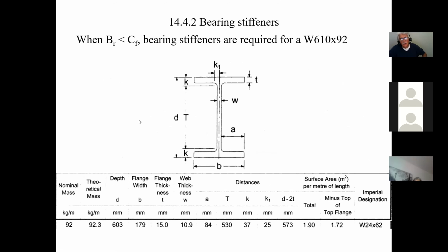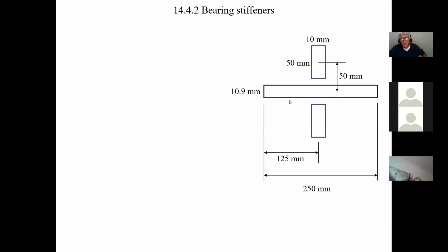Okay. And like I said, all the information is there. And like I said, that was my column. And this is where all this good stuff comes into practice. How do I calculate the moment of inertia of this cross section? How do I calculate the Rx of this section? Well, simply take the moment of inertia divided by A. And you can appreciate that, when you take the I, the base times the height, this height here of 250 is going to be much greater than the I of this one. So that's why I only bother calculating it with respect to one. In other words, I calculated with respect to the weaker one, which was this one here in this case.